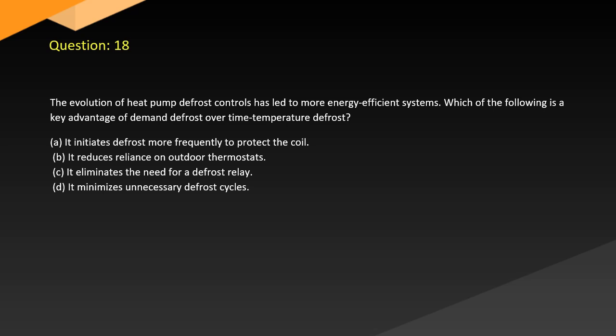Question 18. The evolution of heat pump defrost controls has led to more energy-efficient systems. Which of the following is a key advantage of demand defrost over time temperature defrost? A. It initiates defrost more frequently to protect the coil. B. It reduces reliance on outdoor thermostats. C. It eliminates the need for a defrost relay. D. It minimizes unnecessary defrost cycles.